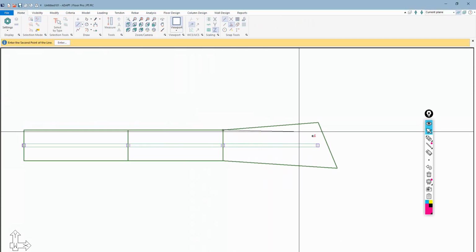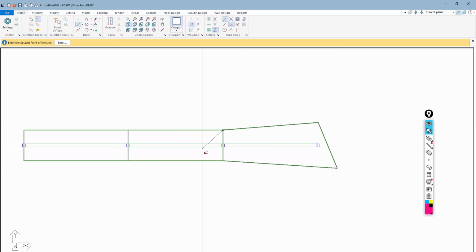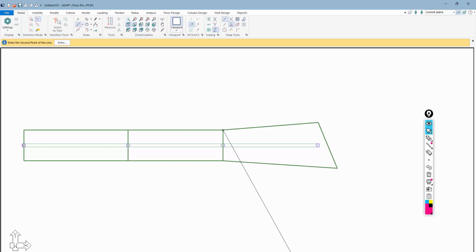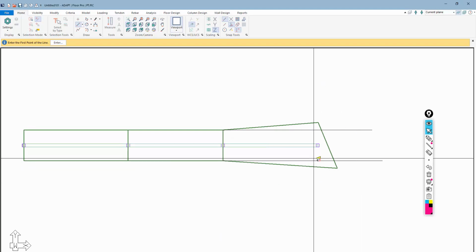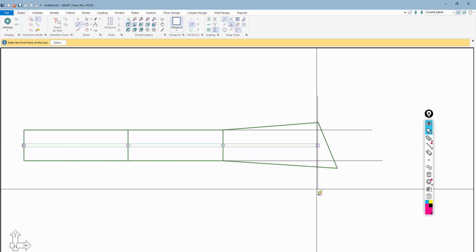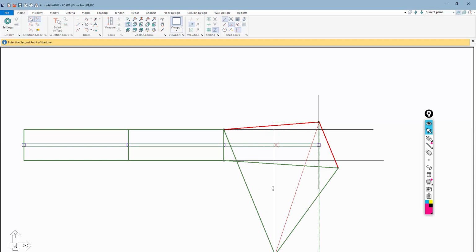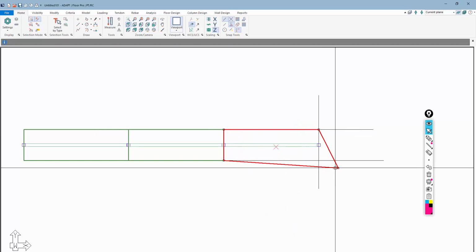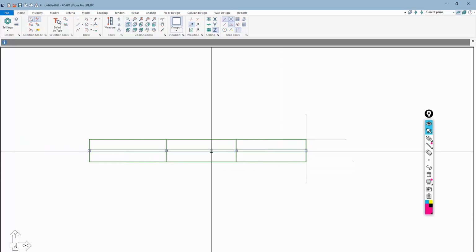Here I want to have this, in the orthogonal, let's say X direction, parallel with these beams. So I could turn on this option for snap orthogonal, and that allows me to align these construction lines orthogonally, and here I can just grab that and now just move it down. So there's different ways to kind of model the components natively and align things. This is just one particular way of doing that.